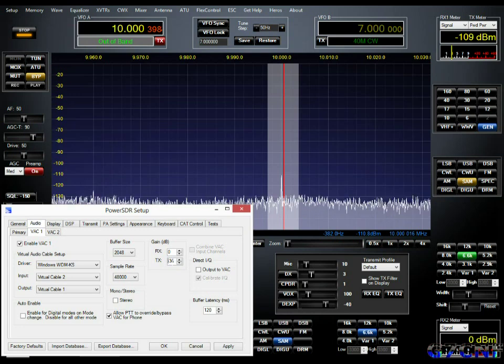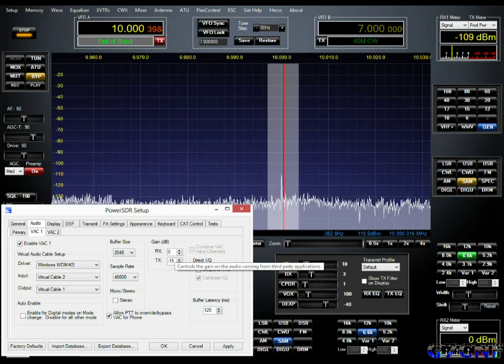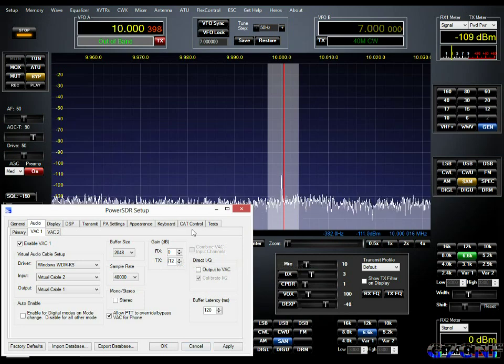To begin with, I recommend pulling that down nice and low, starting our sound card program, putting it into TX dummy load, etc., and then adjusting our TX output until it is at a suitable level. And in fact, I will take a look at that in another video briefly, because I can show you how to set it up so that you have the maximum possible output but retain the minimum possible IMD from that output, and it is possible.